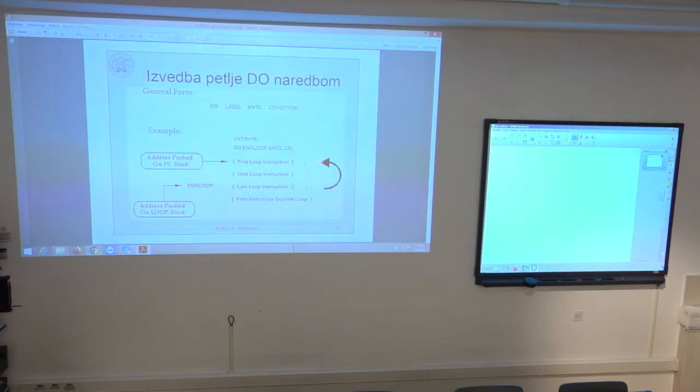And furthermore, with a conditional jump, you would also have a pipeline stall. As I described previously, all of these architectures are based on an instruction pipeline. If the program counter is not sequentially incremented, then the address that was fetched in this fetch part of the pipeline was the wrong instruction, because it had to branch back to the first address of the loop. Normally with a conditional branch, you would have this stall, and wait states would be automatically inserted until the proper address is finally fetched and the pipeline is full again.